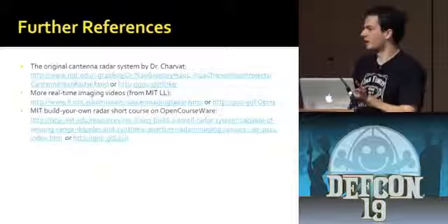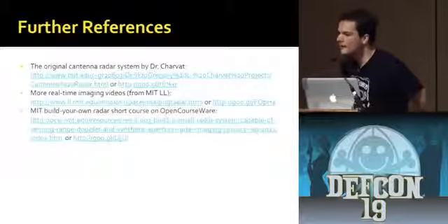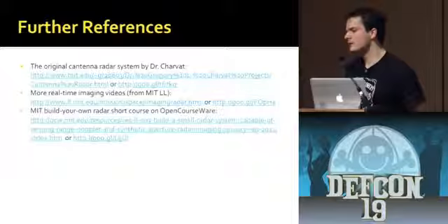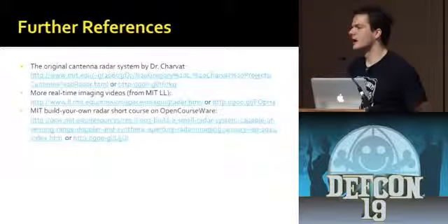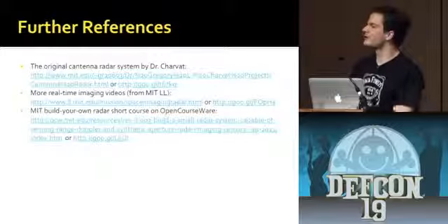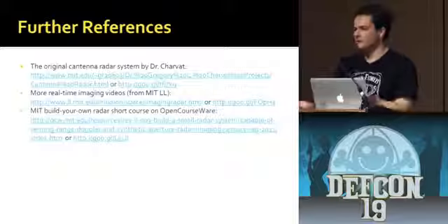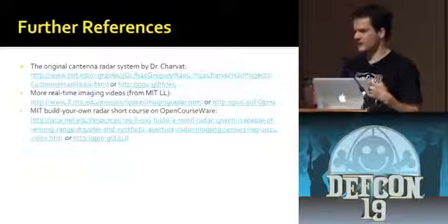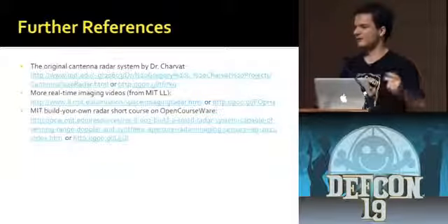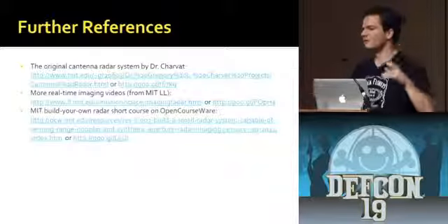But if they're not transmitting, it's not really a big deal. Is the upper frequency limit defined by how easily you can obtain a reference signal? The frequency bands that you can operate in, there's a few bands. You pretty much are stuck to the ISM bands if you want to do this legitimately, because those are what's licensed for this unrestricted or pseudo-unrestricted use.